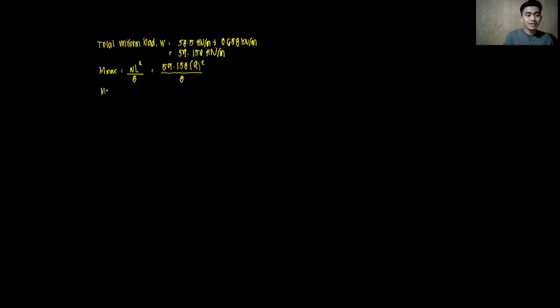So M max is 59.158 times 9 squared all over 8, which is 598.97 kilonewton meter.